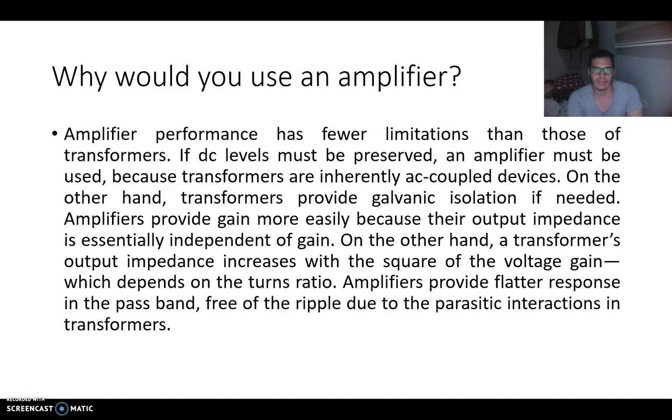Why would you use an amplifier? Amplifier performance has fewer limitations than those of transformers. If DC levels must be preserved, an amplifier must be used because transformers are inherently AC-coupled devices. On the other hand, transformers provide galvanic isolation if needed.